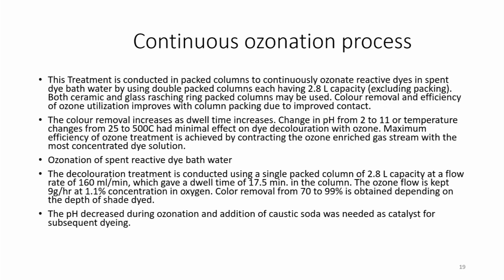The pH decreased during ozonation, and addition of caustic soda was needed as catalyst for subsequent dyeing. So, what happens is that when this ozonation is carried out, one needs to continuously monitor the pH, and that is done by adding the caustic soda.